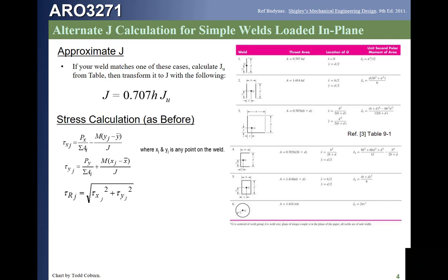One more word of caution is in order, and that's that these are all for a weld loaded in plane. What that means is that the weld is all in the same plane, as you can see, and any forces and moments also cause stresses in the same plane, which means your forces actually lie in the plane and your moment is perpendicular to this plane. If all of that is true, you have an in-plane planar, 2D weld, and you can use this approach.